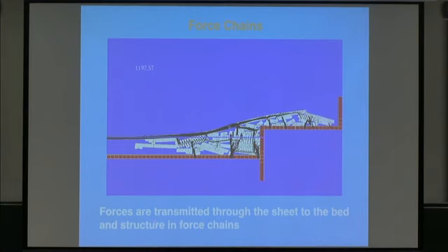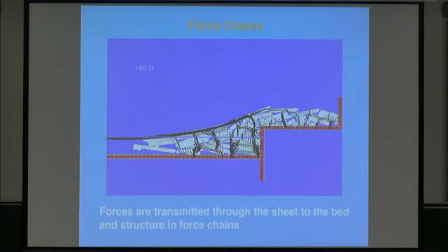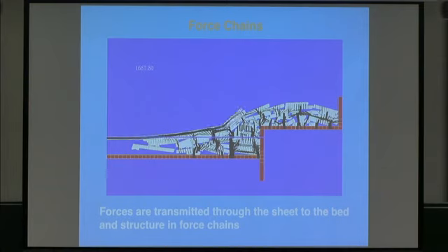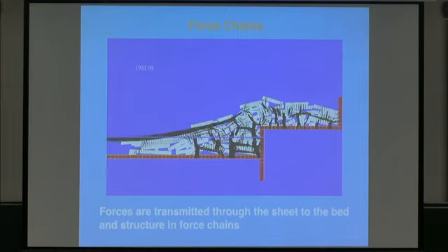What are those black lines? Those are the forces. Thickness is the magnitude, the direction is the direction of the force. So just normal force? No, also sliding force. Oh. So you see sometimes the directions are oblique, so that's a bit of a sliding component and a bit of a normal component. You can see it easier in the aggregate when you see the chains line up.